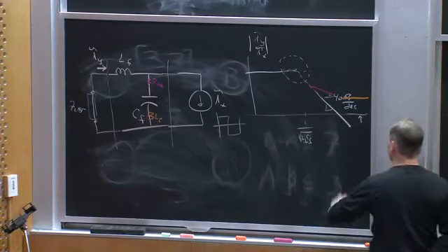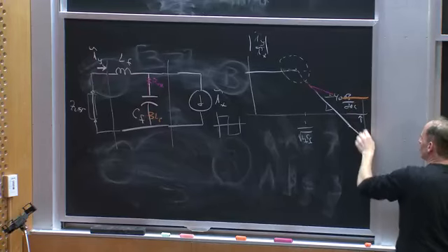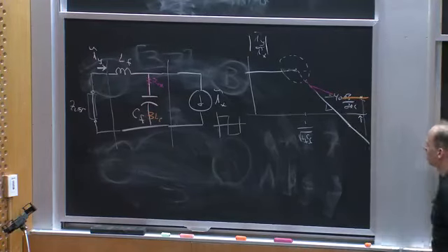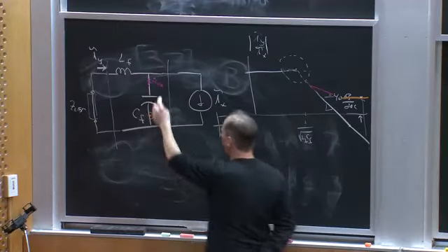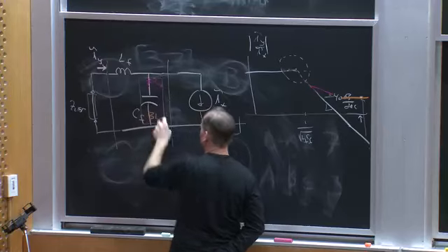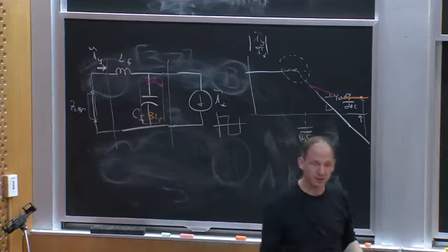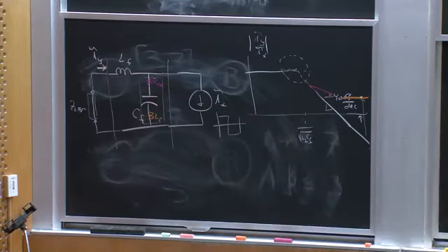So I might be thinking I'm going to be way down here, but really my attenuation is up here, and I don't get nearly as good a performance as I hoped. So this could be due to internal component parasitics, okay? Or it could be due to layout parasitics, how I place everything on the circuit board. Parasitic inductance and resistance is one thing I worry about. Parasitic capacitance is another thing I worry about, okay? So that's just a quick review of last class.